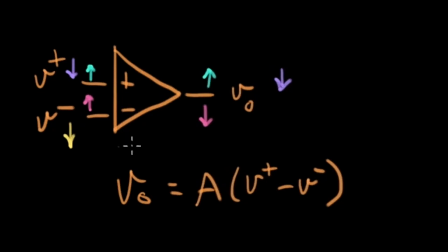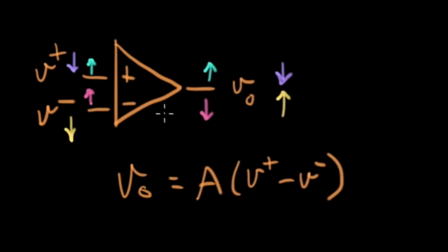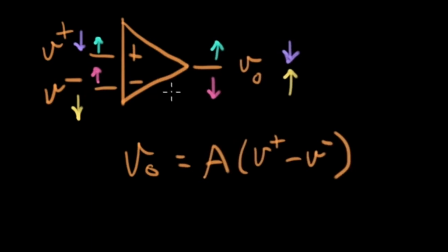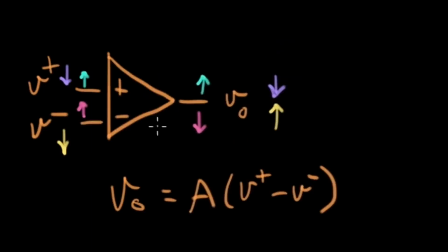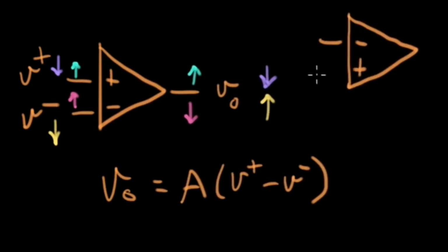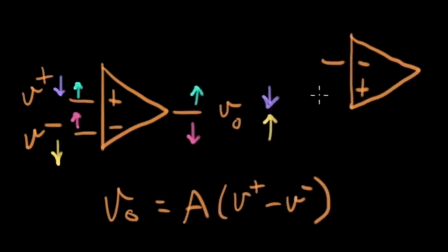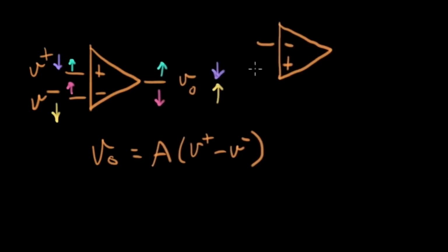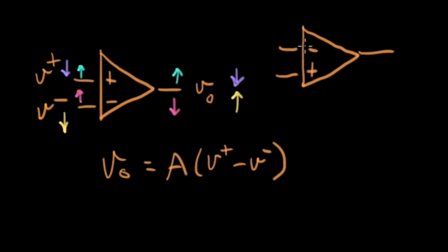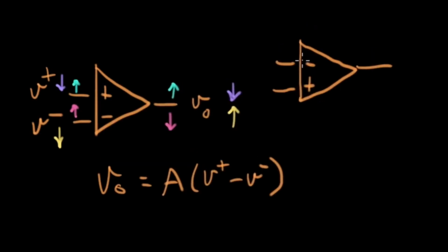This is the same amplifier, written on the page with the inverting symbol on the top and the non-inverting symbol on the bottom. So as you look at a schematic with an amplifier in it, one of the first things to do is glance at what order these symbols are in, and keep that in mind as you read the circuit and try to understand what it does.